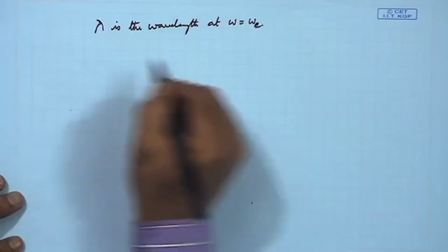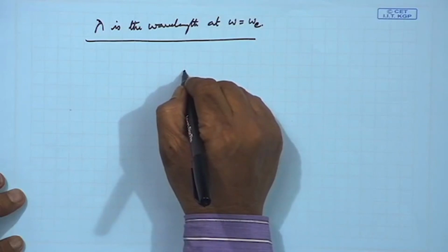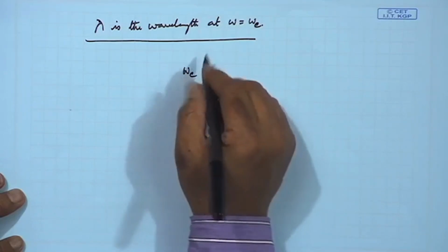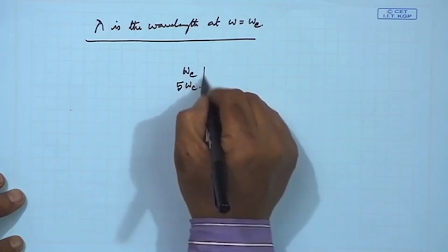Now, obviously, this means that at other frequencies the impedances of these lines will change. So, they will not represent the prototype lumped inductance and capacitance properly, but there is a periodicity: I have omega c, then at 5 omega c again the element values will match.